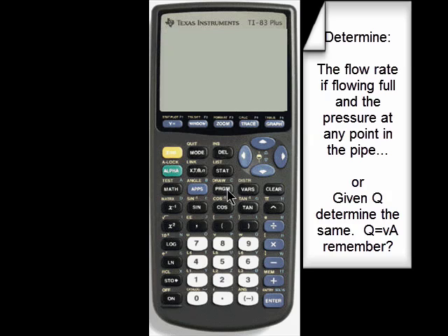So once you get that set up, you go to the Moody diagram and you know, if epsilon is the surface roughness of the pipe on the inside of 0.01 feet and the diameter is 1 foot, then my relative roughness is 0.01 and I have a friction factor in the order of 0.039.